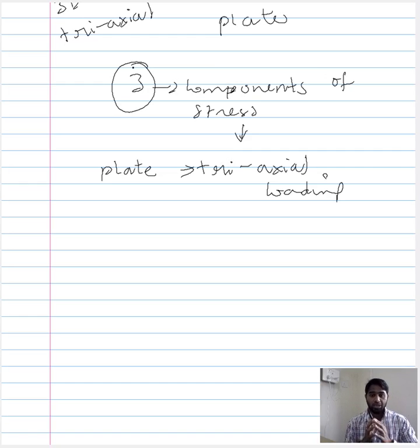And now when you take a three-dimensional setup similar to that of a plate, wherein 2 dimensions are significantly higher than 1 dimension and the face has a significantly larger area than the other sides, it means that the number of stress components required to describe the mechanical condition experienced by a region within that three-dimensional material, again under triaxial loading, is just 3.